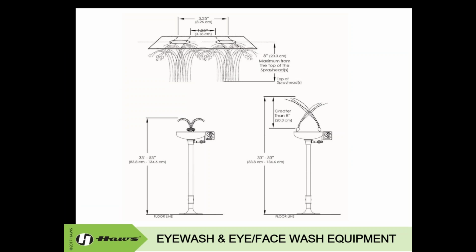On your screen, you can see a couple images. The top one is showing where to place the eye wash gauges in the eye wash streams. At any instance at 8 inches or less, those eye streams need to hit the eye circles. If they are not, we are not in compliance. That is a big part of the annual testing, and as OSHA comes by and does an audit, they will absolutely check for that. You may see out in the industry, and we have definitely seen it, too much flow. I do understand that the ANSI standard has minimums, but some of these pieces of equipment are installed improperly, and it almost looks like eyeball pressure washers, and that's not something I'm going to want to stick my eyes in and not something you're going to want to stick your eyes in.